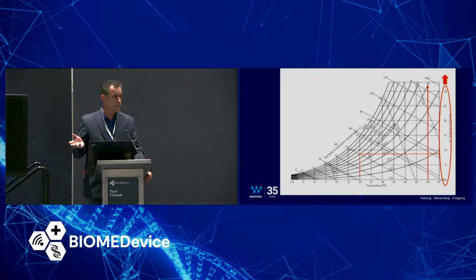And then you get your real-time samples back and you don't even see this. So you're like, well, what's happening here? And there's a lot of digging around and scrambling. So the point is that, one, look at the scope of your testing, accelerated aging. Are you looking at the packaging or the product? And two, if you have a product that has sensitivity to humidity, meaning sensitivity to low humidity, determine what is an acceptable humidity before you introduce humidity into your accelerated aging program. Okay?